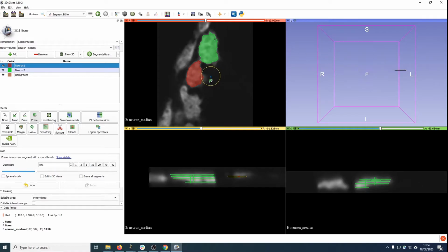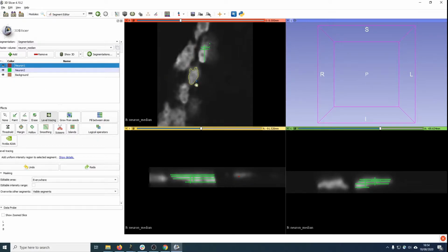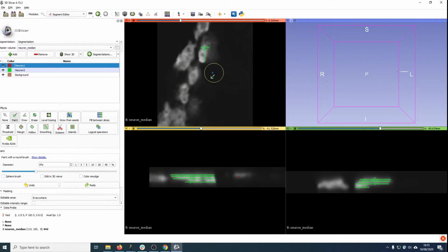So one thing which you need to know is you don't need to do it for as many of the slices. I mean, the more you do, the better, but you can get away with labeling a few. Maybe I'd say do three or so in the XY plane, and maybe 2 each on these 2 views, and that should be reasonably good. The main thing is you want to make sure you label the background, the space between the cells, as background,